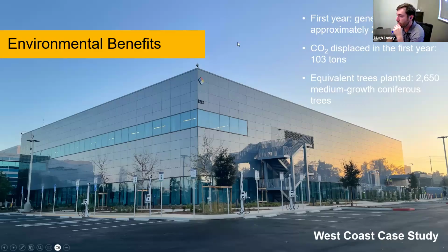And then we had 35 unique shapes to finish off the corners. And that's what you can see on the west wall there. You see basically some smaller panels right as it approaches the corner. And those are the custom sized panels that we fit in there to finish off that facade, matching up with the mullions and so forth, just showing the power of those custom sized panels.